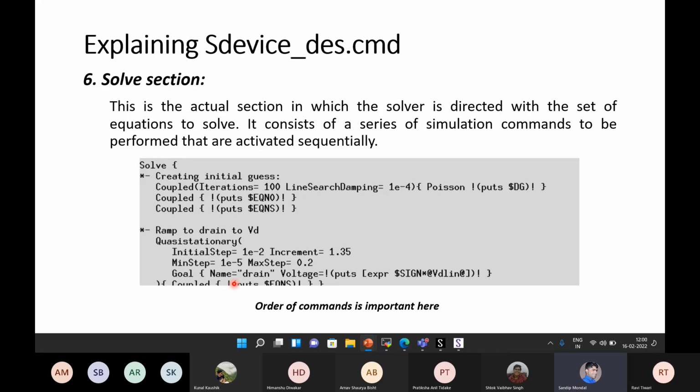We'll get more detail when the transistor part is started. This is just the way we do it in the experiment. We raise the terminal voltage slowly, step by step, like 50 millivolt steps or 100 millivolt steps.